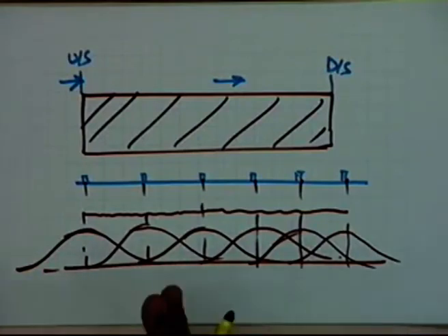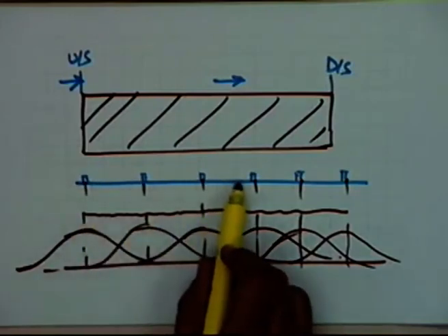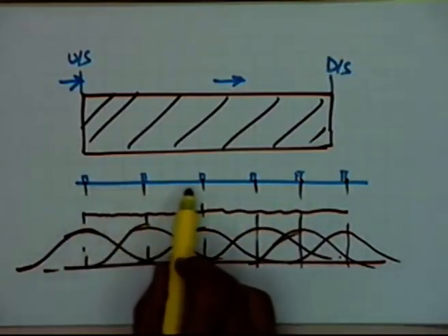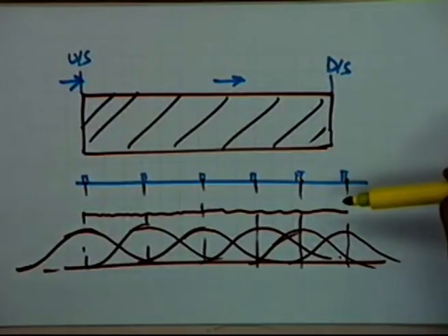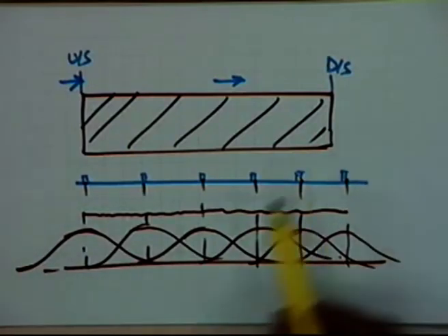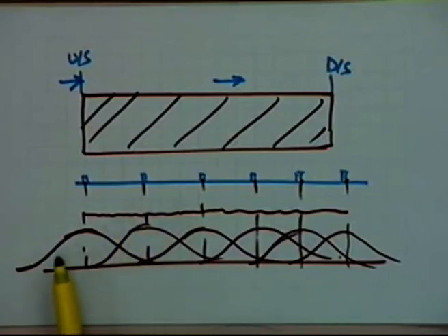So it is the overlap which is important, how each individual sprinkler head is spaced at some spacing. That spacing is what we are interested in knowing. That is part of the design. When you design the sprinkler system, later on we'll see what the spacing should be, because that will be a function of the distribution pattern.